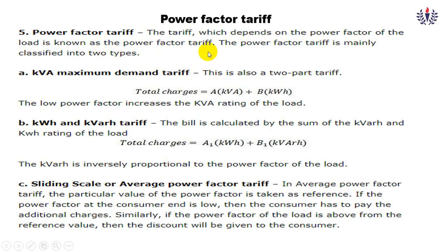Resistive load is unity power factor, inductive load is lagging power factor, and capacitive load is leading power factor. If you use more inductive load, that is motors, you will get a lagging power factor. So based on the load, the power factor will change. Based on the power factor change, we will apply the power factor tariff.